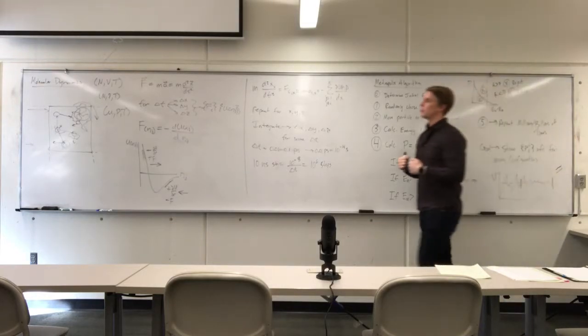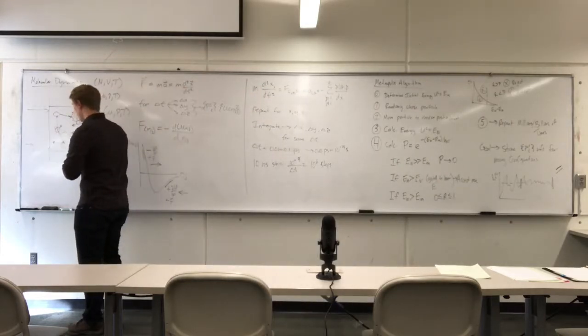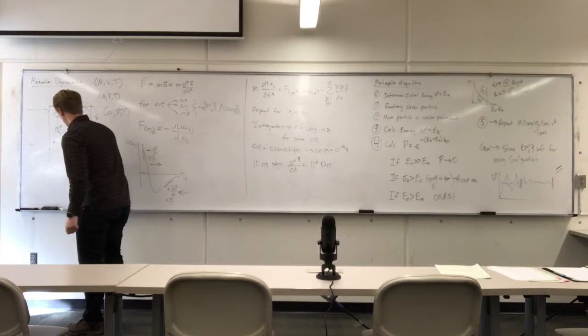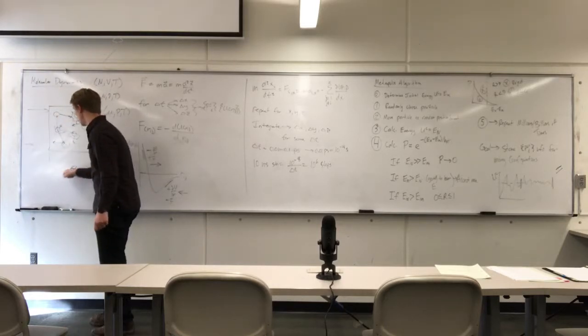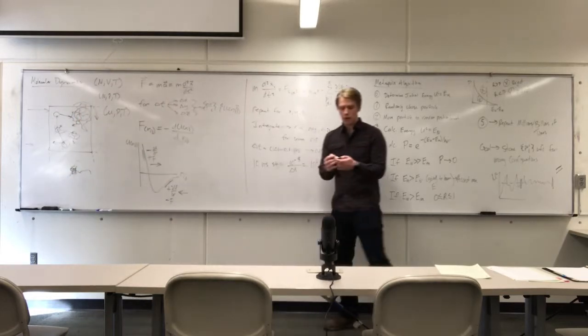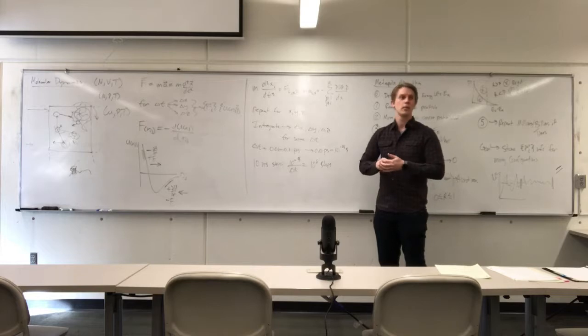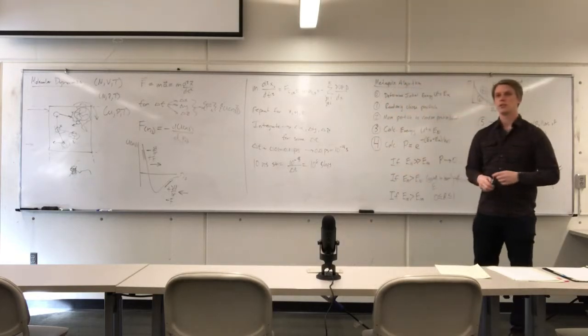So the other things you can do in simulations is you can set your initial configuration. Let's say you're looking at a polymer, and you want to set the polymer to be really collapsed, and you want to see how long it takes for the structure to open up. Then you're kind of at the whim of how rigid or how flexible that polymer is, how quickly it relaxes. So depending on the goal you're trying to do, there's lots of considerations to determine how long you need to run the simulation for.